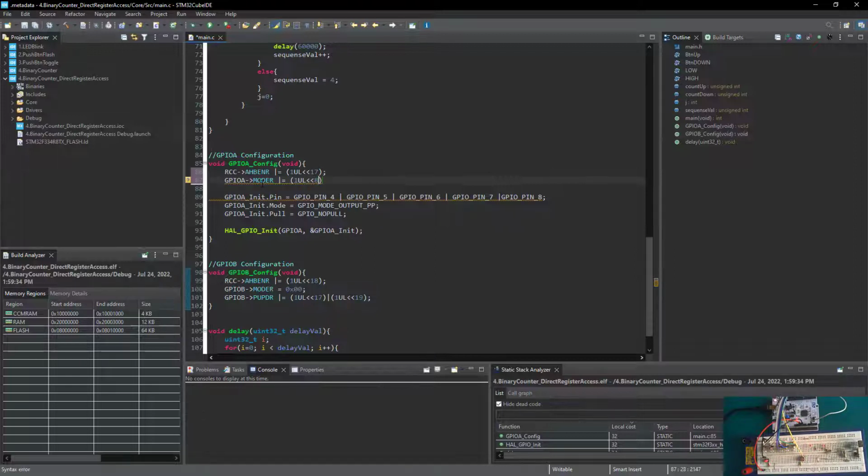So that basically means I'm shifting 8 times and writing a 1 into that bit and leaving the other bit 0. Then I'm going to move with another OR operator into the next bit. So I'm going to just copy all of this and paste it right there. So 1, 2, 3, 4, 5. So those are all my 5 pins. Let me just put a semicolon there.